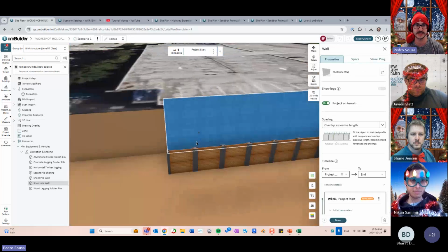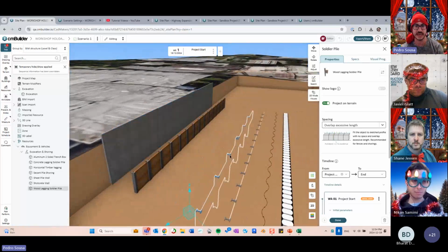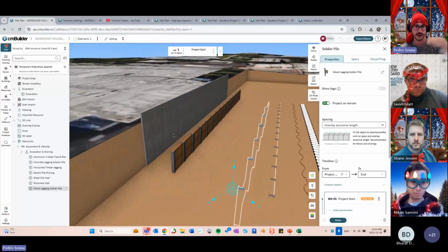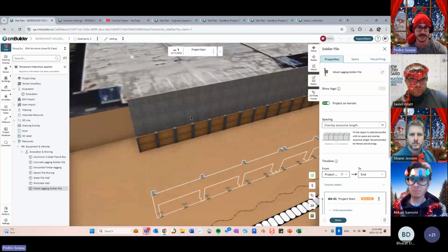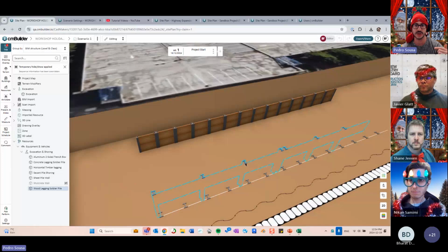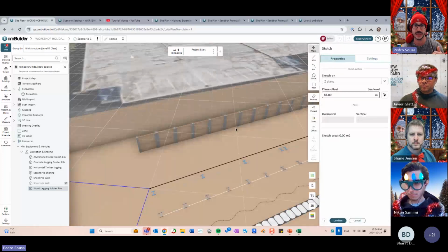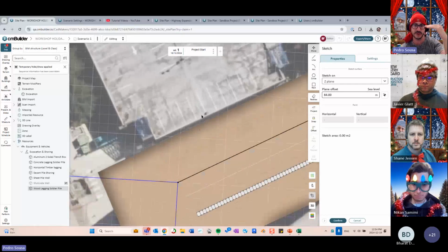So this is one way of inputting shoring, but for several other shoring methods, you're going to see that it will grow downwards. All of these shoring elements that you place and grow downwards are that way because we want to use the line input for those elements to follow the grade on the top part of your excavation.